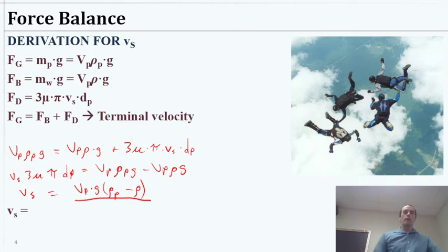Before I write that out, one thing we'll notice here is essentially that settling velocity is a function of the difference between the density of the particle and the density of the water. So that difference is key, and we see it clearly right here now, which gives us some confirmation. And if you do forget exactly, you'll actually have this on your equation sheet, but just to think about it, as you're going, it's that difference that drives your speed, right?